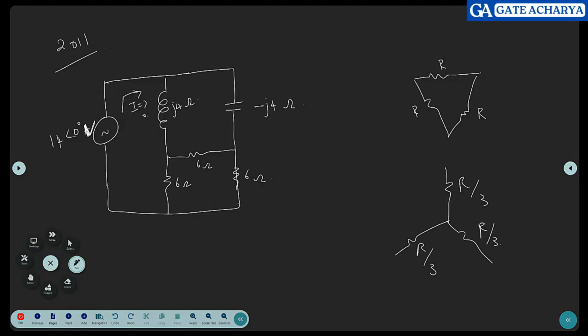I already told you that the star network will be smaller resistors than the delta resistors. How small will it be? If it is all same, it will be 1/3. For example, if they give 111 here, it will be 333. So just remember this, it saves a lot of time. You don't have to go back into those equations every time.